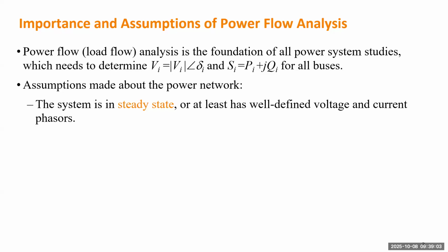But if the system is not in steady state, but in some dynamic state, which means the voltage is changing, the frequency can also change. For instance, if you remember the assumption we made to create the concept of phasor, we mentioned the system needs to operate at a constant frequency, such that when we write the voltage or current phasor, we don't need to write that omega.